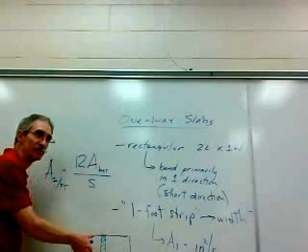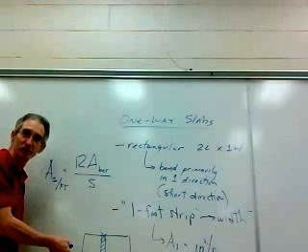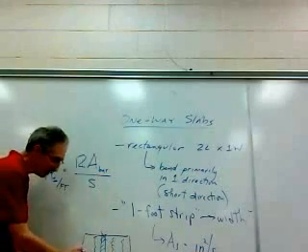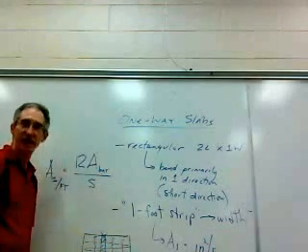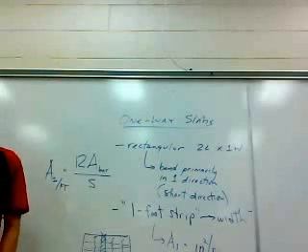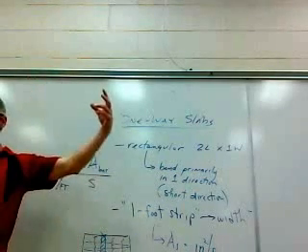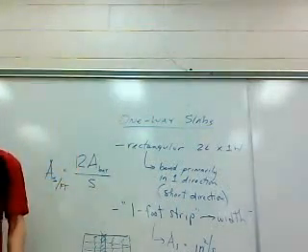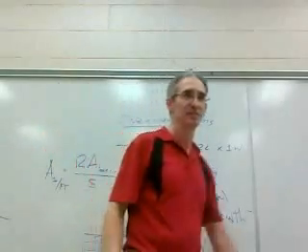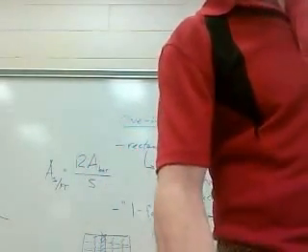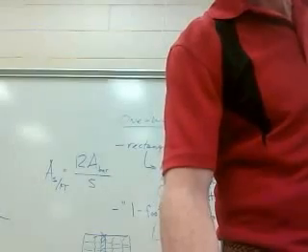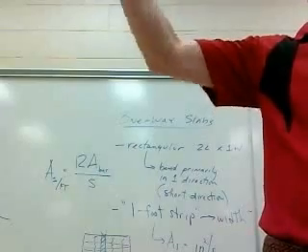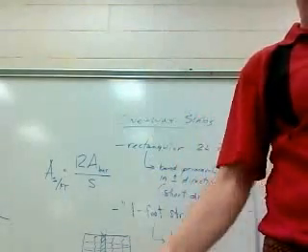Go to our hallway out there. The hallway is long and narrow. Where do all the shrinkage cracks occur? Like this, right? So if we had bars running this way, that would help to catch it, wouldn't it? All right? So long, narrow, the shrinkage occurs in the long, narrow direction. Probably it occurs in the other direction too, but primarily in that direction. And do we design for that? One-way slab? Yeah, actually you do. I wouldn't say it's designing for it, but there is a little formula that the code would give you that says you should use this much temperature and shrinkage steel.